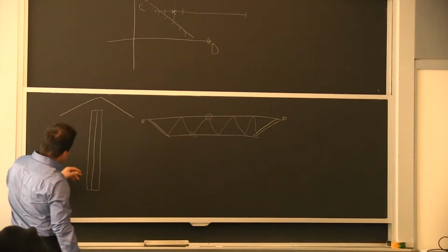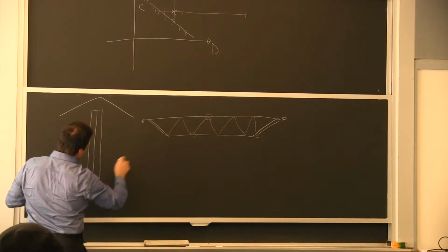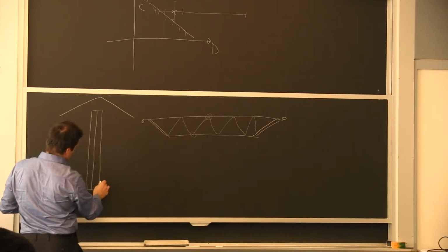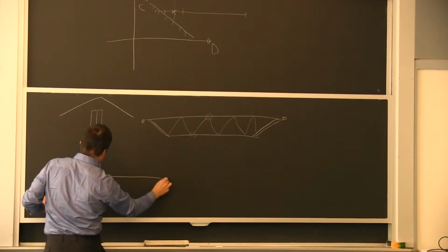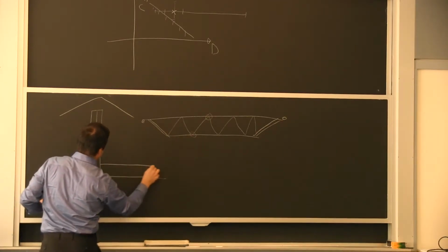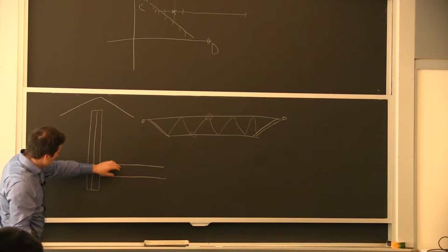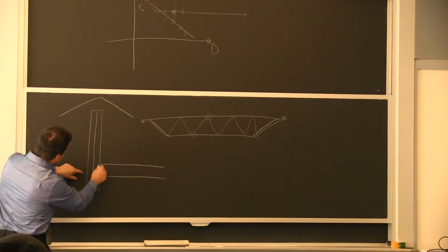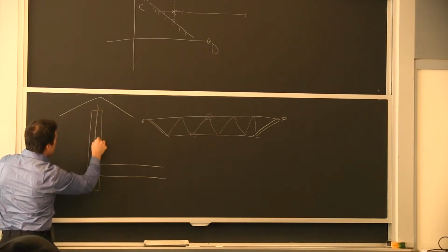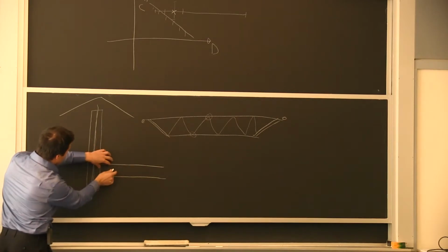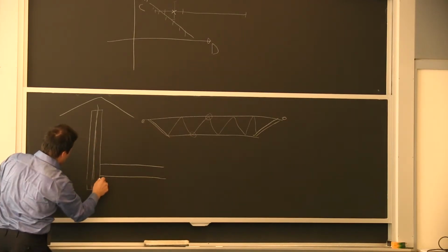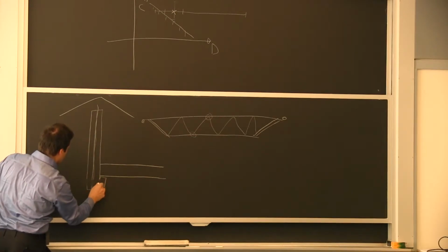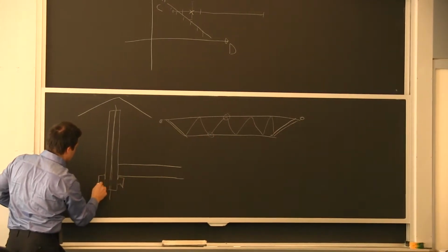They had a big truss going each way, and they had these chords. This is exactly how it was. So say I make it this way. This is the lower chord, and essentially these were two different sections. You take this side, you take this side, you put them together, and you have a bolt going around here to connect them together.